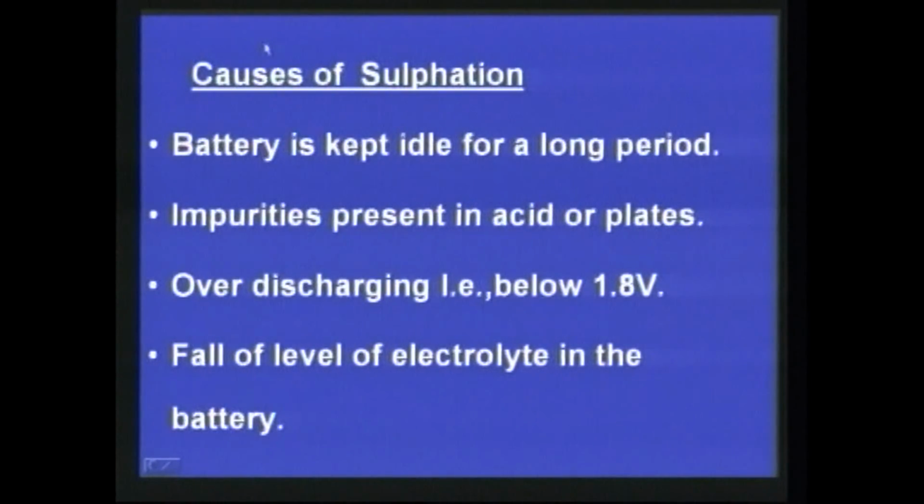The causes of sulphation. When the battery is kept idle for a longer period, sulphation is caused. Also, sulphation is caused when impurities are present in acid or plates.